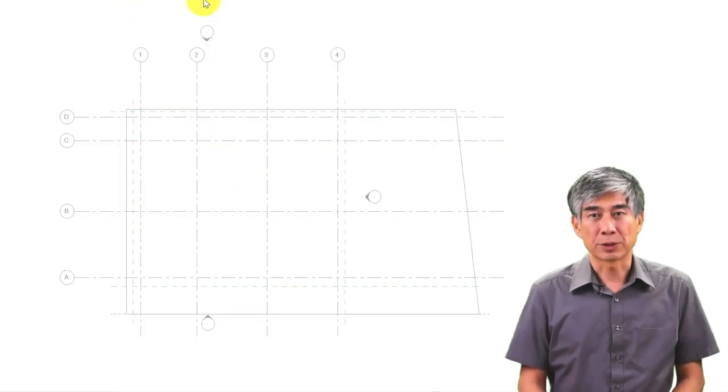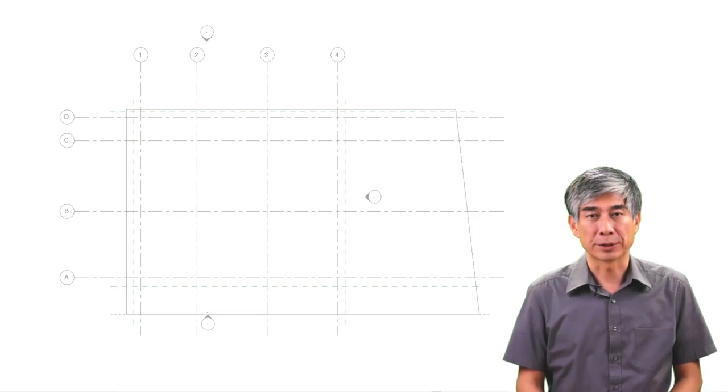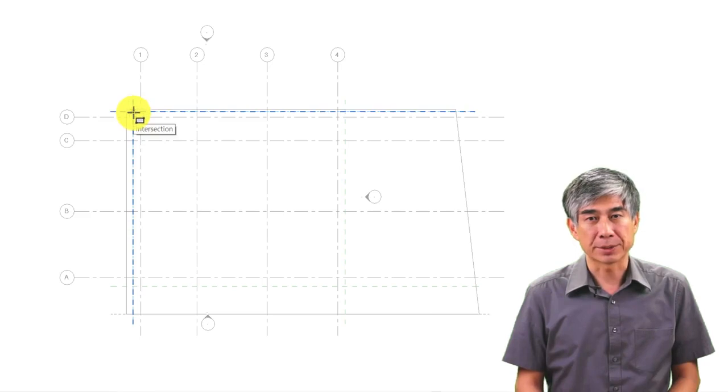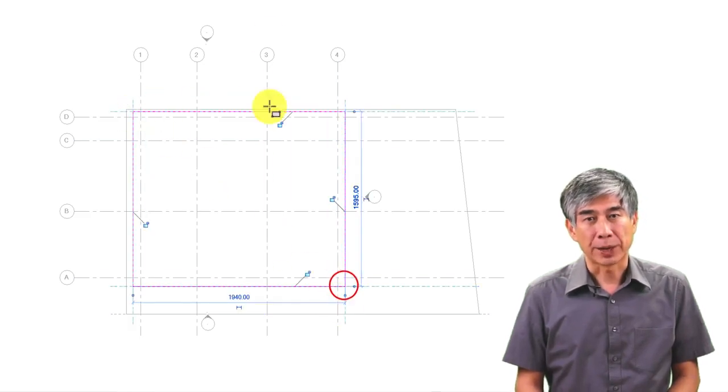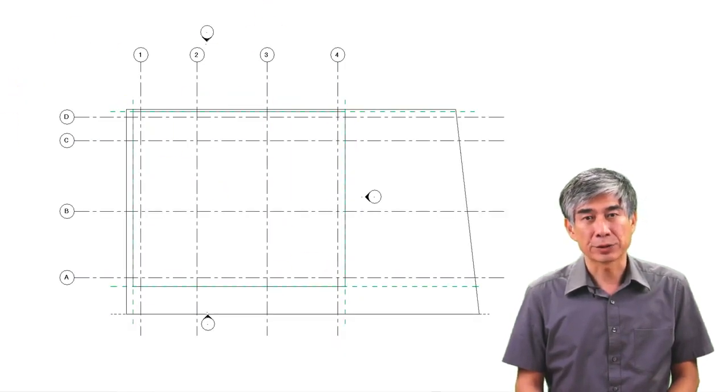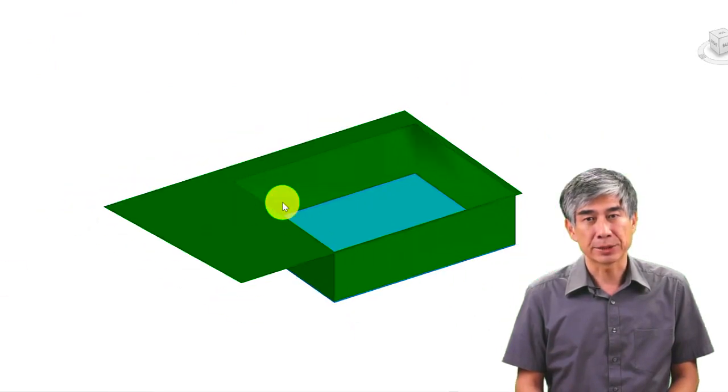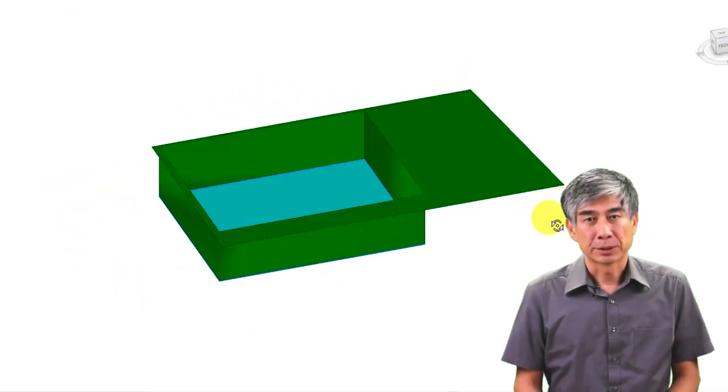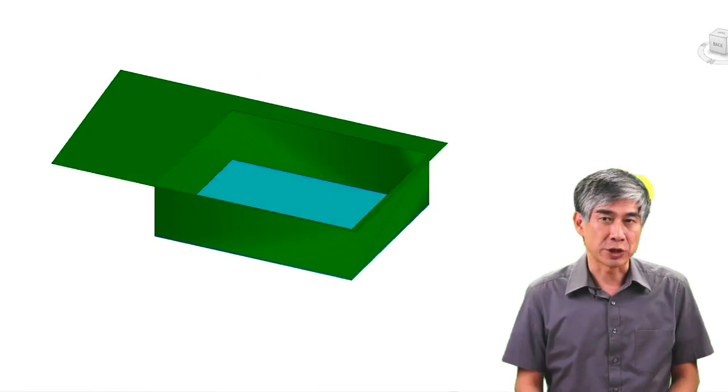In this session, we are going to set up a Revit project. All of the essential steps have been introduced in the fundamental course. Here, we just need to combine the steps, including creating grids, creating levels, drawing property lines, building up topography, and excavation.